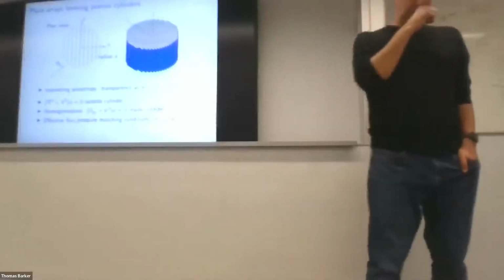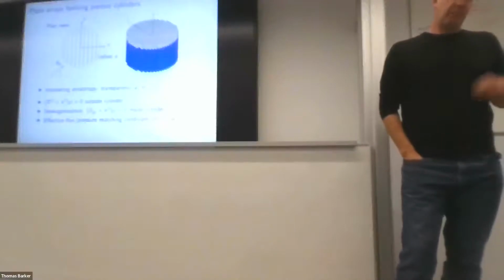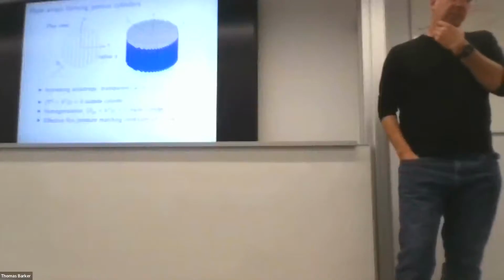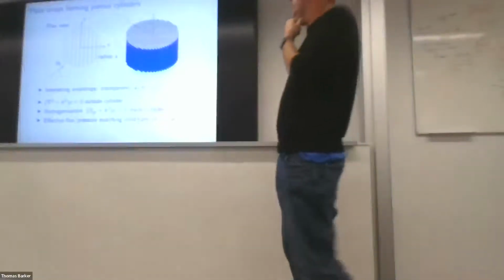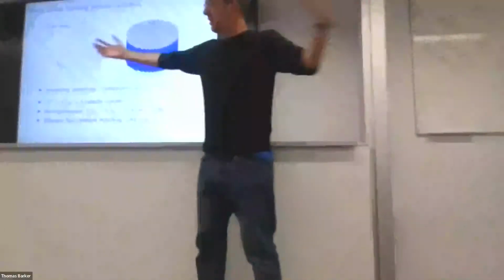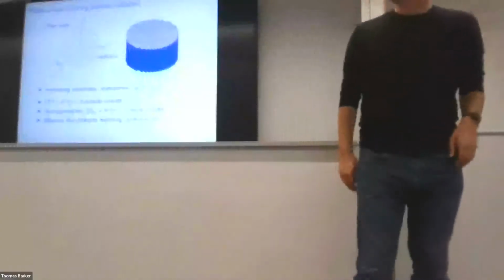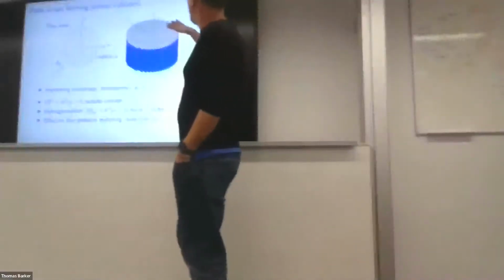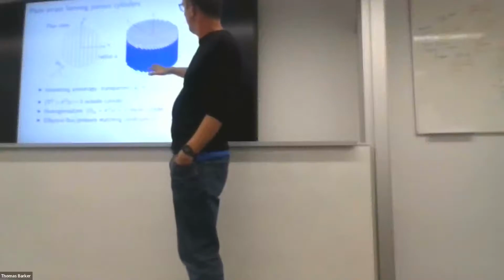Okay, so the final thing to look at is the effect of these bathymetric plate arrays when they extend uniformly throughout the depth. So here I'm back to using phi again, and I can use it for all frequencies. I don't have to use shallow water theory. And instead of having a semi-infinite domain or a strip or a slab of this bathymetric material, I've now arranged it in a circle. I'm using a circle because I can do semi-analytic things with circles. So this is what I'm imagining. I've submerged this thing, as is suggested on the right-hand diagram, this sort of toast rack through the water.